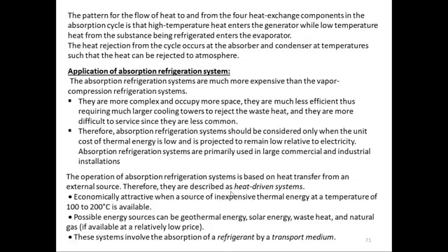Economically attractive when a source of inexpensive thermal energy at a temperature of 100 to 200 degrees is available. Normally a gas turbine or a steam engine gives out energy at 350-400 degrees, maybe 600 degrees centigrade. But the minimum requirement here is that you have 100 to 200 degree temperature energy available, then this will be an economical option. Possible energy sources can be geothermal energy, solar energy, waste heat, and natural gas if available at